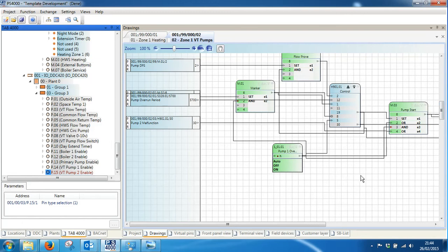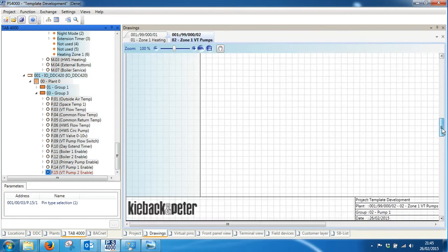To reset the failed pump, what you have to do is in the user interface you can manually change the status of the pump to on or to off, and then put it back to auto, and that will reset the lead pump logic. Alternatively, at the end of each day the logic is reset, and the following day the pumps will try to reinitialize the correct lead pump.